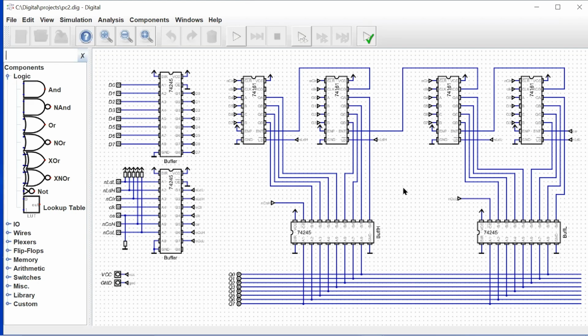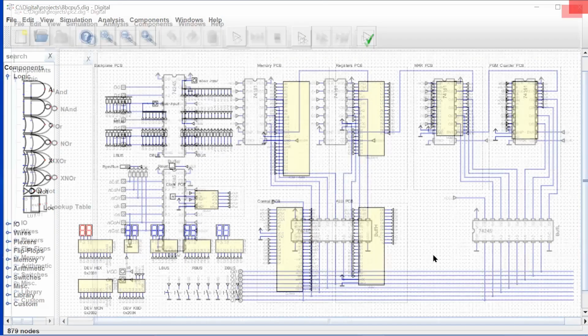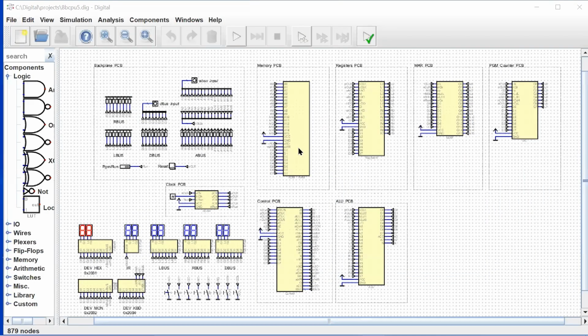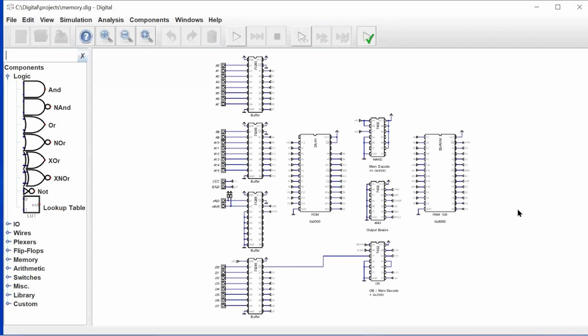and we're back to individual logic elements here for our counters. But we see that we have introduced the 245s for all the signals coming from the backplane. And we already had 245s for the output signals going to the backplane. But you see that, and we'll see that in all the designs. We have our 245s for input and our 245s for output. Right? And we could take a look at the memory circuit. All right, so here is our RAM and our ROM circuit. Again, we see a heavy use of the 245s for buffering.